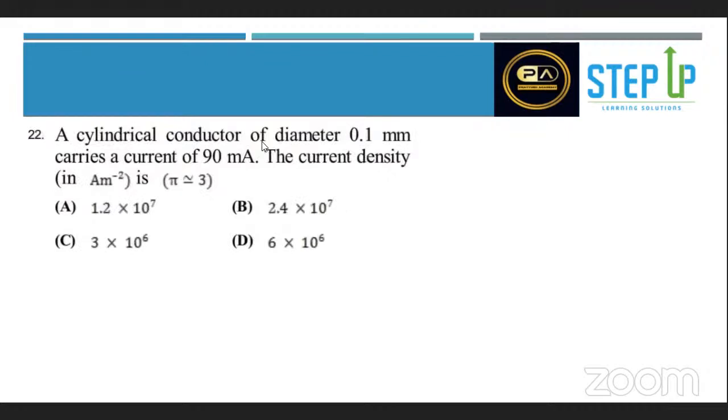Okay, I can explain. The previous question basically said you have to find the minimum capacitance. To find the minimum capacitance, we have two options: either connect them in the reciprocal way for the minimum value, or just add them, which gives the maximum value. In case of resistors, series R1 plus R2 plus R3 used to give the maximum value, and parallel used to give the minimum value. But in case of capacitance, this goes opposite.